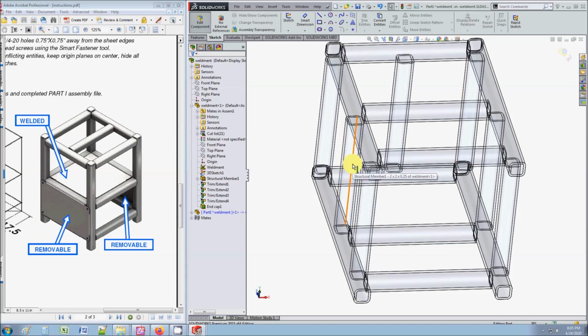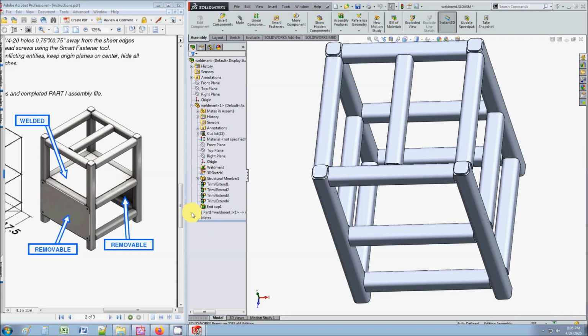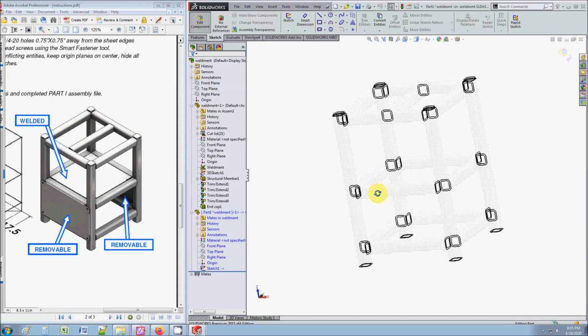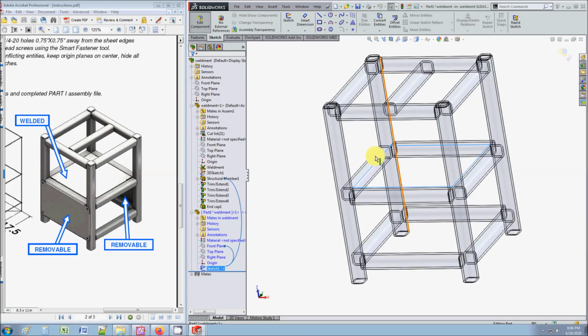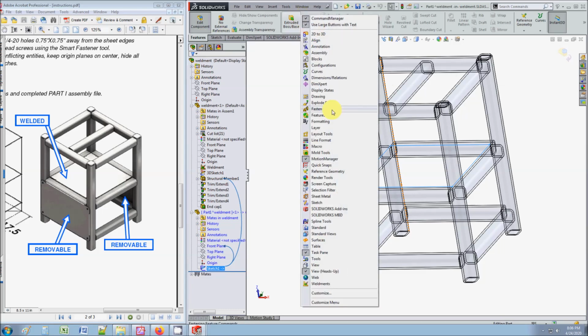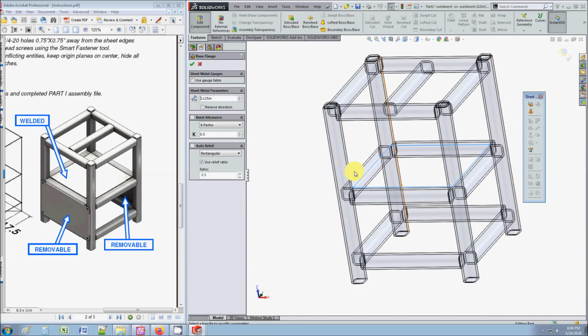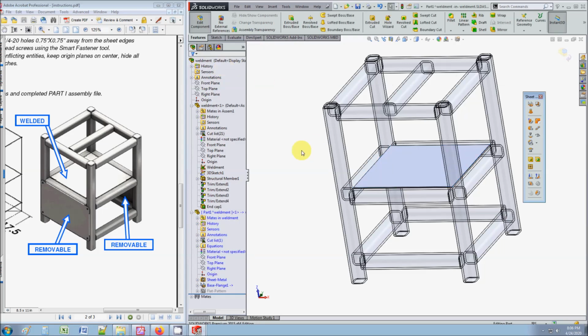So if you notice, I did not use any dimensions to create that sketch. So anyways, here's my sketch. Let me go back to part mode. I'm just going to click edit part mode. And here's my sketch. I need to turn this into a panel. So what I'm going to do is turn on my sheet metal. And I'm going to start out with the base flange tool. And this time we're going to use 1/8. Okay, 1/8. So everything is 1/2 what we did during the exercises.